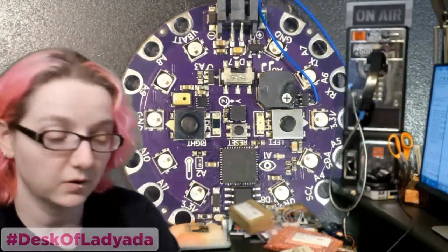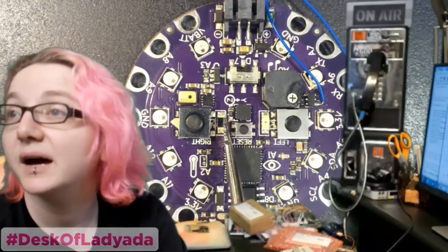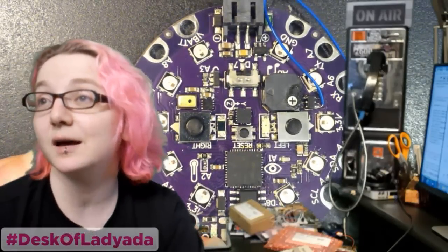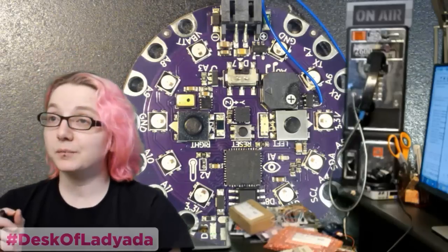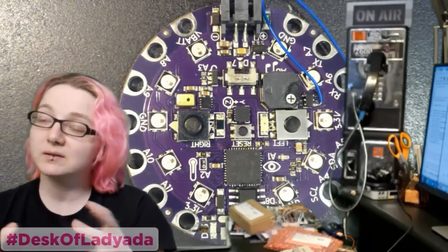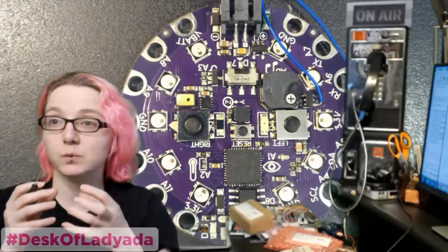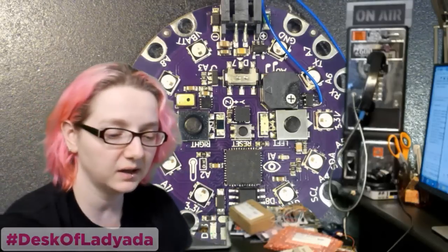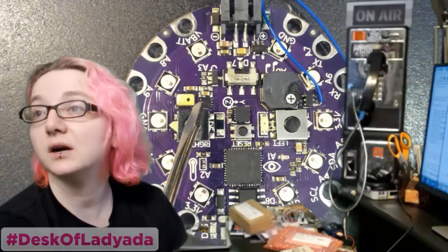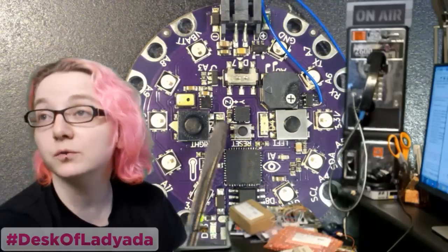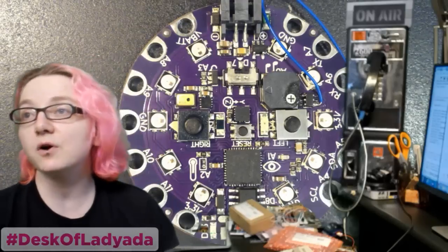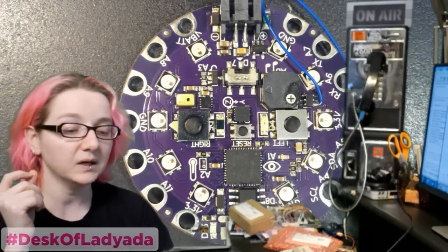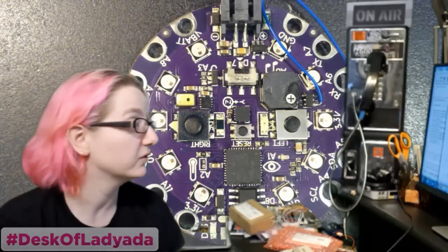Okay. So over here you can see that black pin diode. And then the receiver chip is actually over here. And then the capacitor and the resistor that they recommend is right next to it. So what actually is nice is, even though this is a little bit bigger, it's about the same size as an integrated all-in-one solution, but I could spread it out. So I could put the receiver LED over here and then the chip down here. They're close to each other, just far enough away that I could use that space intelligently.